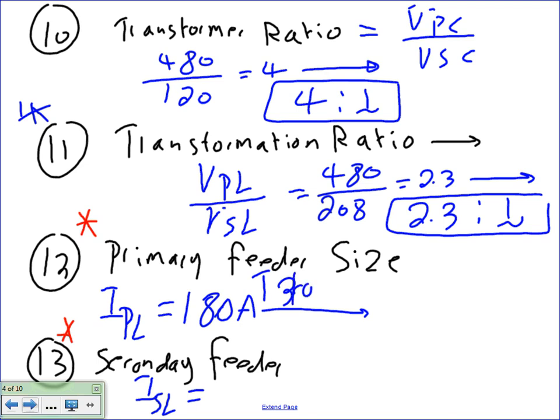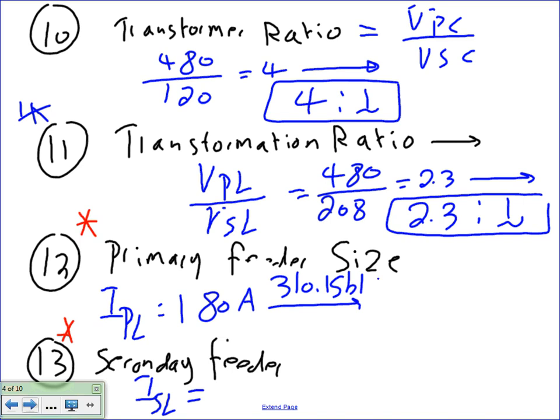Table 310. We're going to go size conductors, right? Immediately. So amps, 180 amps. Take this one to 310.15B16, the table based on 310, and you're going to go under which column? Column 75, right? Why 75? Because it's higher than 100. So you're going to go 75.